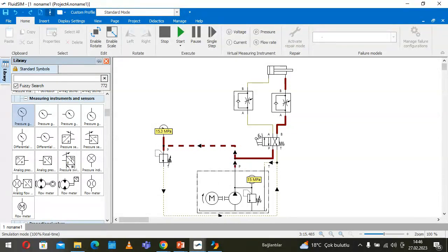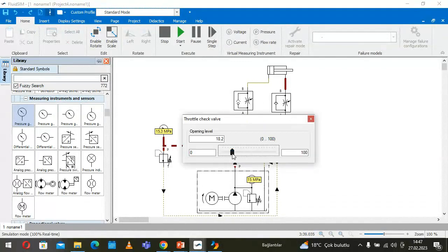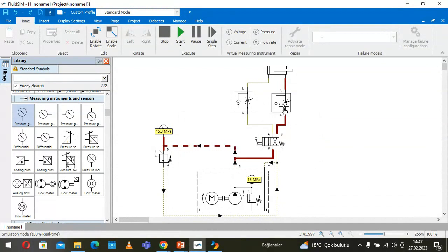Okay, you see, if I start the motion, you would expect it to stop. But it does not stop. Why not? Because I use the restrictor here, and because of the restrictor there is a resistance, so the pressure increases. If I open it fully, then during the motion you will see the oil stop flowing via the pressure relief valve into the tank. You see now.